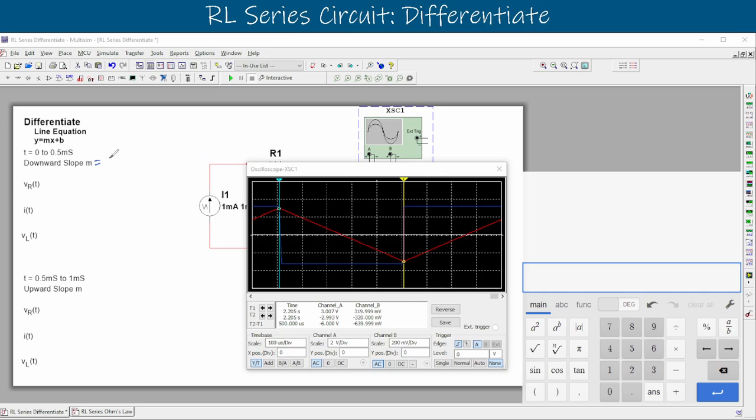So we'll take our change in voltage and divide it by the change in time, and that requires two different factors, right? We need to know two values for our voltage and two values for our time, which we have right now. We can say that the change in voltage was our second voltage here, the voltage at 0.5, and that's this mark right here. So it's our lower one. It's T2. And we see T2 is at -3. Right? And then we'll subtract that from the voltage that we had initially, which is this upper voltage here. And that is the first voltage. That's 3 volts. So we'll call that V0. And we'll divide that by the two time intervals. So we know that it's T at 0.5 milliseconds.